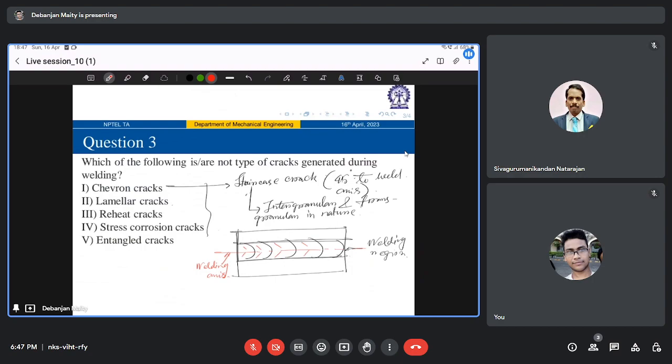Now this liquefaction cracking, what is happening is that by this phenomenon, melting can occur even where the peak temperature of the local weld thermal cycle is less than the equilibrium solidus, right? And hence the phenomenon can occur in the heat affected zone also. So obviously in the heat affected zone, melting does not occur. It does not go to the actual melting temperature of the base metal, but somehow the peak temperature of the local weld thermal cycle is less than the equilibrium solidus and melting is happening, right? Why is this? Because of some constitutional liquation occurring during non-equilibrium heating, and there can be development of a solute gradient around the second phase particles in the matrix phase, which leads to melting at the eutectic temperature, right?